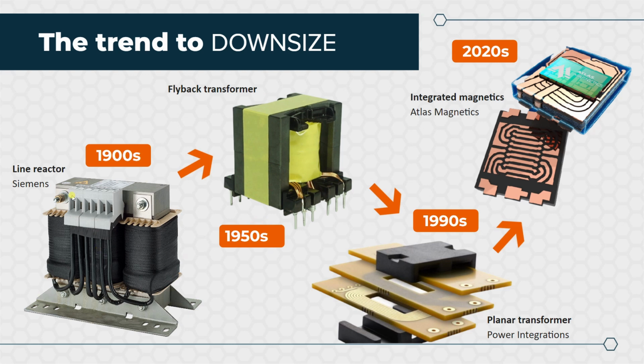The next breakthrough happened about 50 years after the first design of those transformers, with the introduction of new materials, more specifically composite materials or ceramics that we nowadays call ferrites. With new materials that have significantly lower electrical conductivity, we were able to use higher frequencies. As a result, we could scale down the size of our transformers for the same power output.